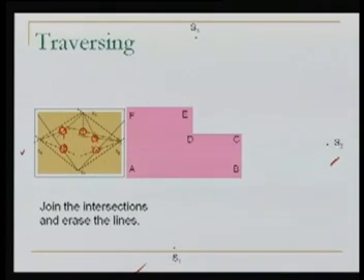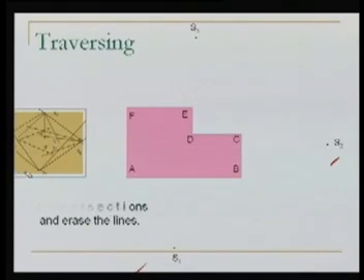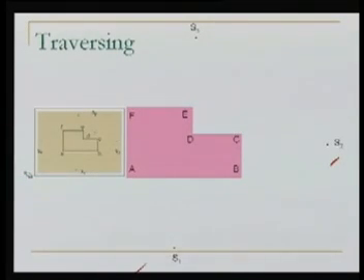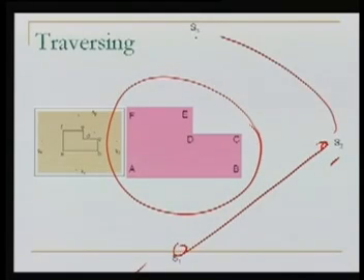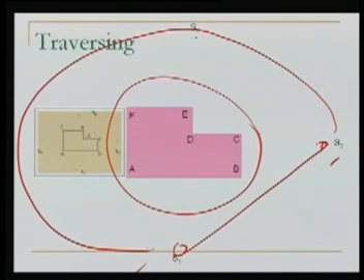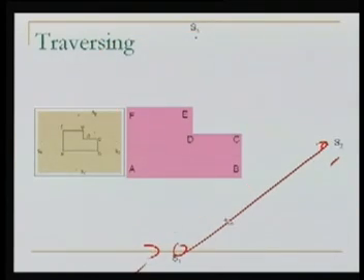Okay, by joining all these points, we will be able to get the map of the area. So for a large building which cannot be covered from only 2 stations by intersection, we rather take a full round, we make a traverse. So this is the method of traversing. In this case, we have taken a large building, but the same thing can be applied for other cases also.